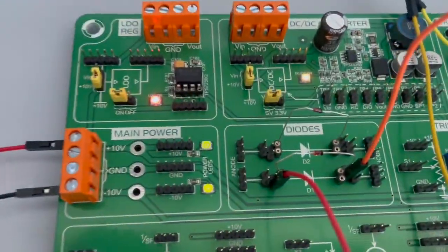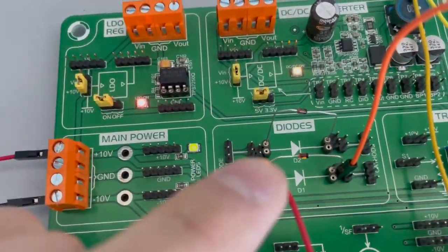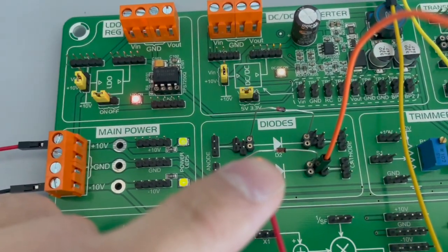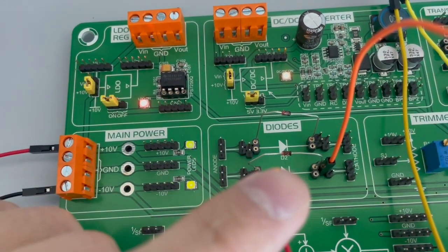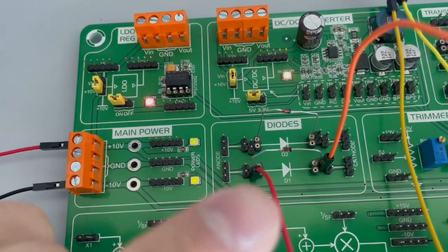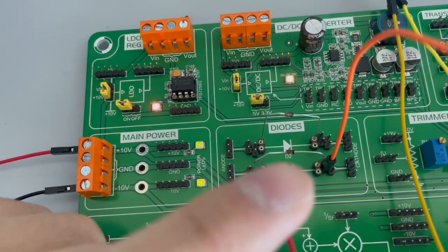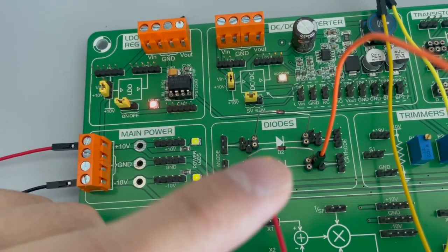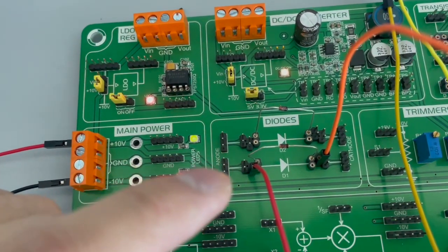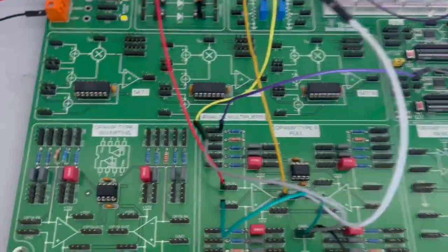So in your packages you should find the diode, and in your diode you're gonna have like a black line. So from right side, if you find the black line, it means this right side of the pin of the diode is negative. So make sure that you connect this black line to the cathode and the opposite line to the anode. So let's first see how the logarithmic or log amplifier is working.